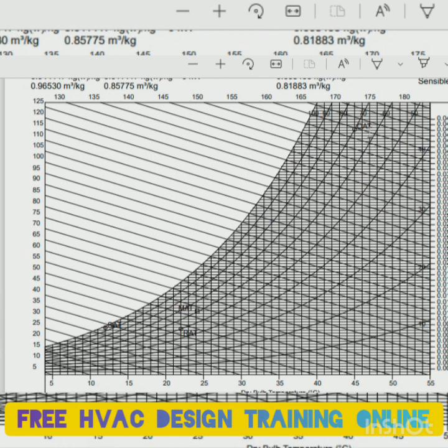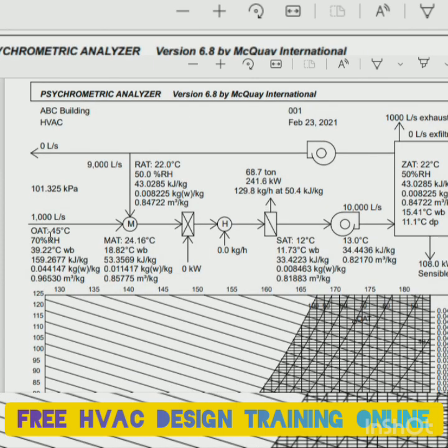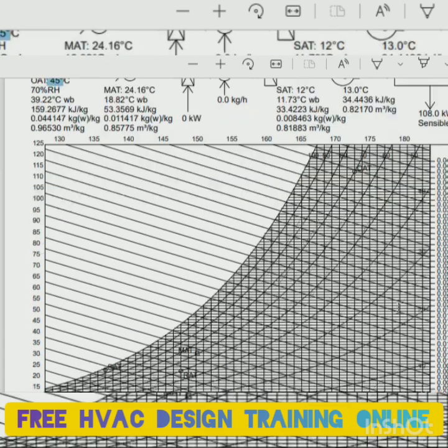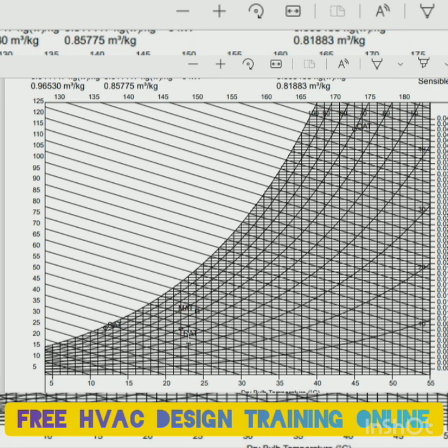This is your OAT, the outside air temperature. We have selected 45 degrees Celsius. Then the return air temperature we have selected will be 22 degrees Celsius. The mixing air temperature will be 24 degrees Celsius. The supply air temperature is 12 degrees Celsius.